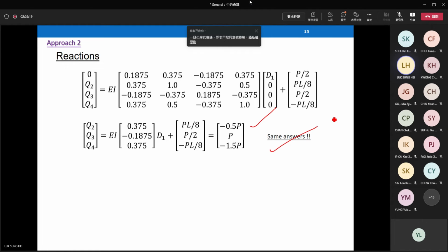So sometimes at the beginning, in step 1, discretization, it's good to think about and have a look to see how to cut the structures. Sometimes some special cutting, just like this approach 2, can greatly simplify the problems. I'm not saying that approach 1 is not correct. Approach 1 is still correct, but it increases the difficulty a little bit. You have to solve a 3x3 matrix problem.